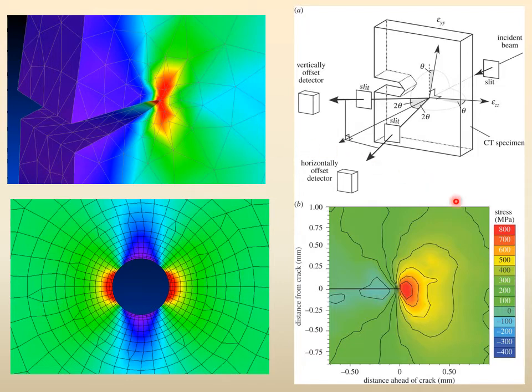And this finite element model, if it is successful, is successfully telling you the stresses and so on. The red ones are high, 800 megapascal. The next one's orange is 700 megapascal and so on. So the distribution is there. And then you can show the same stress distribution in a radial type of graph, right? In a radial type of graph, in a contour plot.